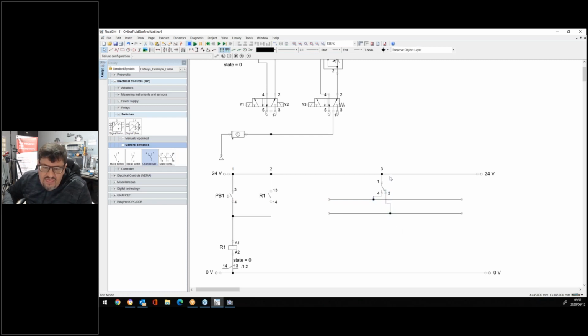Right there. Now this relay contact needs to also be attached. It needs to be attached to R1 again. I hope you guys can see it. That means the moment when I energize R1, I need to change my changeover contacts. Guys, I know there's a small delay. Please keep up with me.